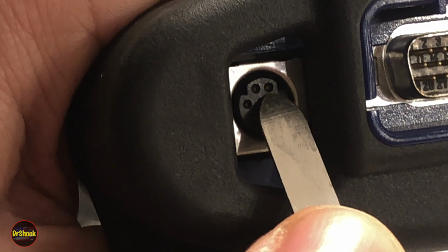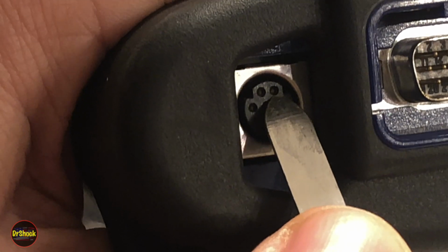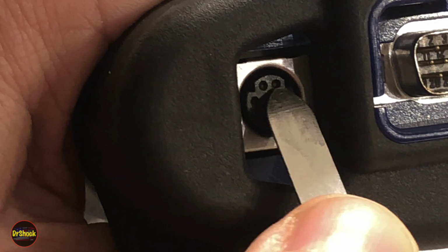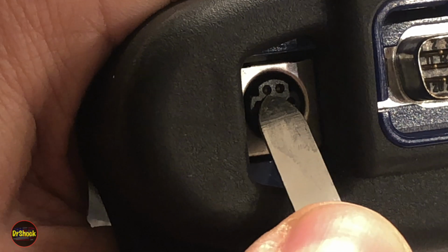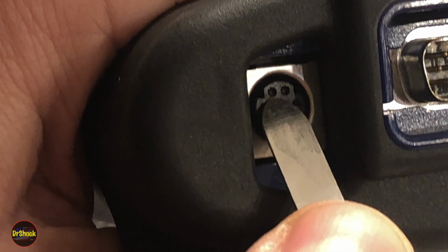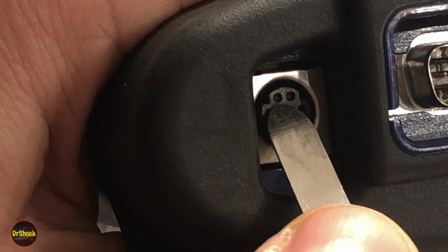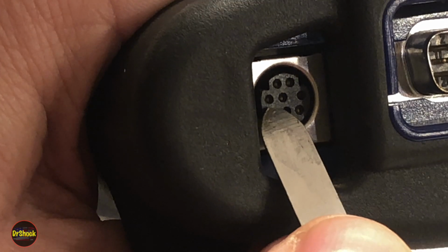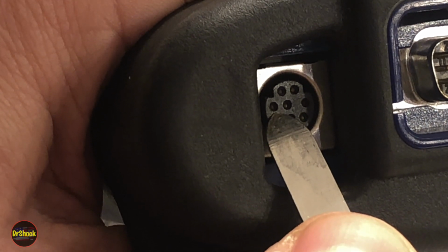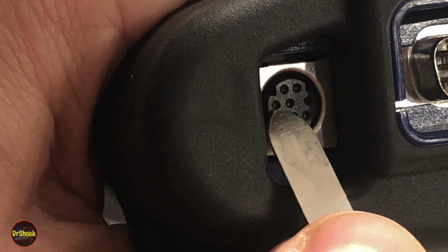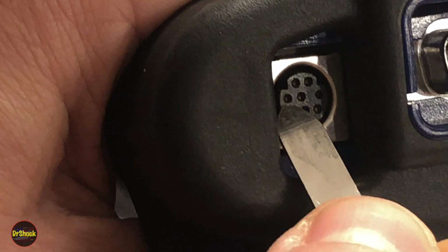And this is what you're going to hook up to the transmit line on the 9-pin coming out of the PC. And then right to the left of it, this pin here is going to be the transmit on the MDI. And of course, you're going to hook that up to the PC's receive line. And then this one right here, in the middle row. So this is the top row, the middle row, the bottom row. In the middle row, this one on the far left is going to be ground.